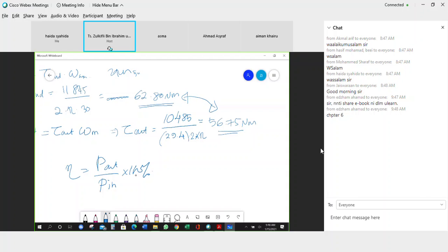You have your jX2, you have your R2, and the important part is on the rotor copper losses. So your R2 includes the slip. So the R2 by (1 minus S) divided by S. That's the part you need to know how to write, where the machine is, where the parameter will be.